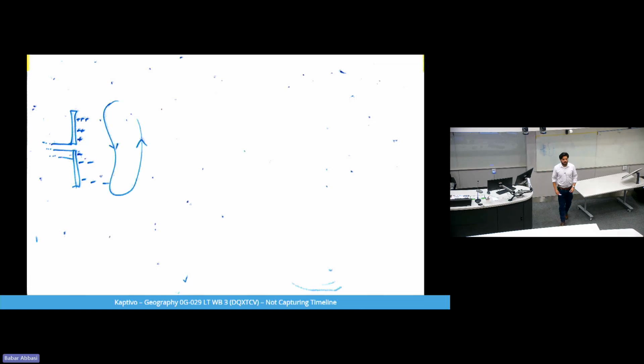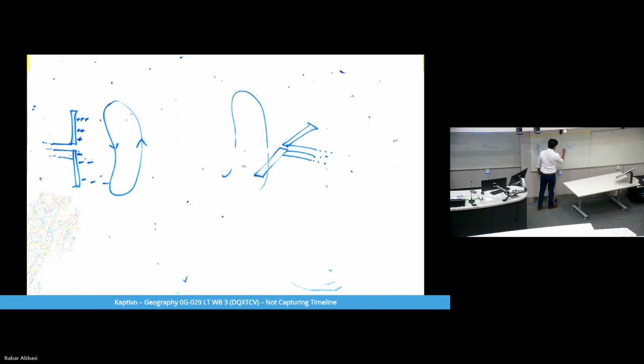Okay. So now imagine I have one dipole sitting like this, and my receiver dipole is tilted 90 degrees. Will it receive anything? It shouldn't receive anything. So if I have a dipole sitting like this, then it will not receive anything because the electric field propagation is along the other dimension.